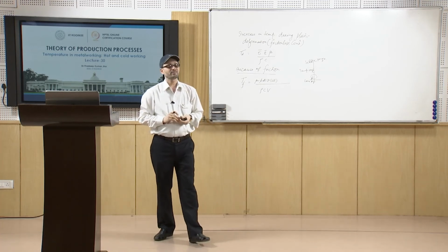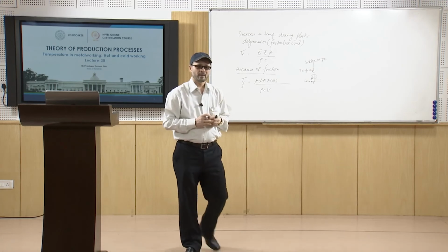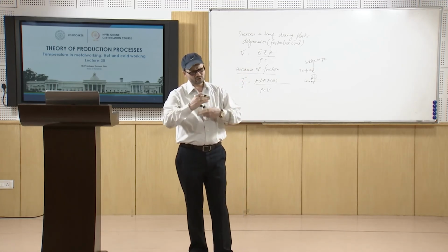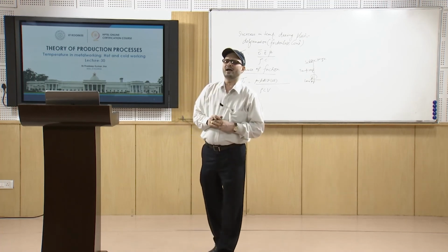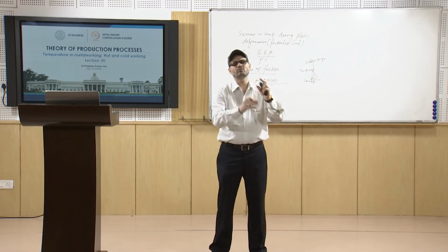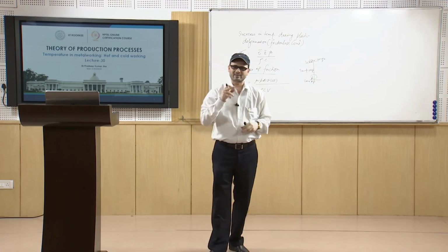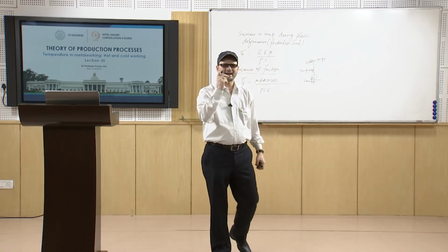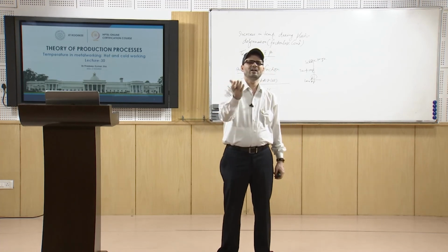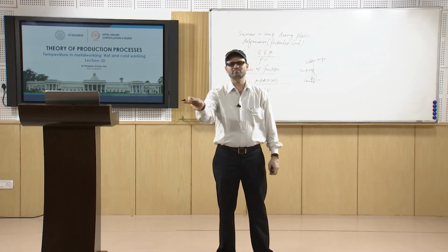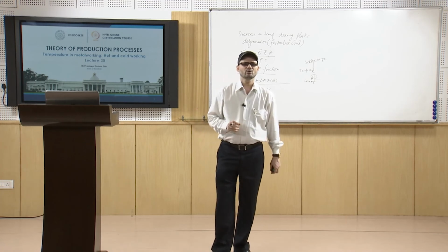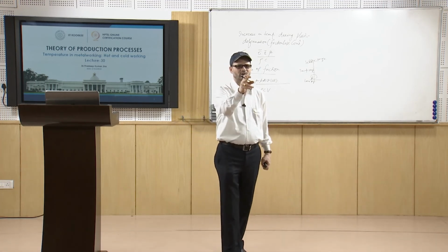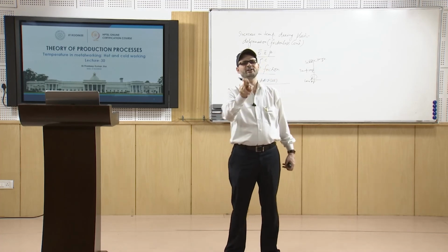So, normally cold working is done in such a way that it is followed by an annealing operation. There you have multiple passes: you do the cold working and then you go for annealing. The advantage of cold working is that in hot working we saw that, because of high temperature, you have the chances of oxide formation reaction. These problems are not there in cold working, but certainly with annealing, what we saw is that you have a cold work anneal cycle.